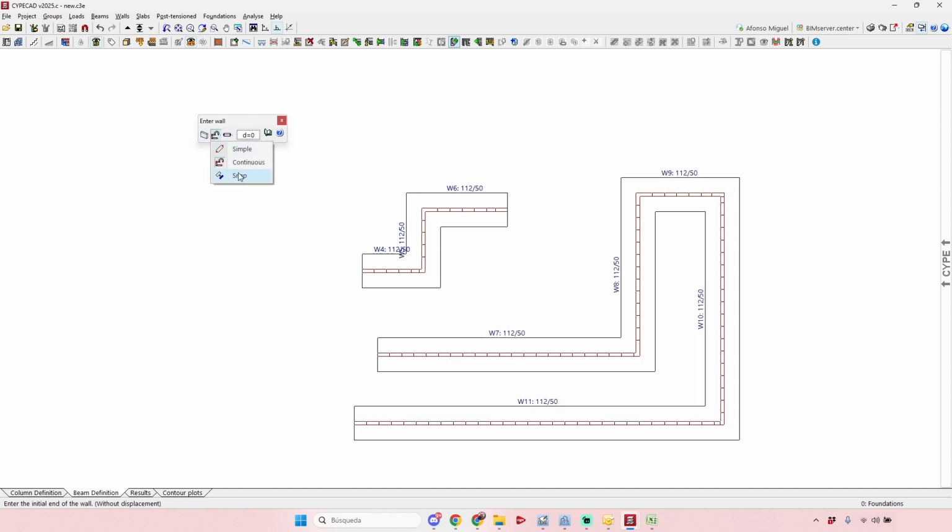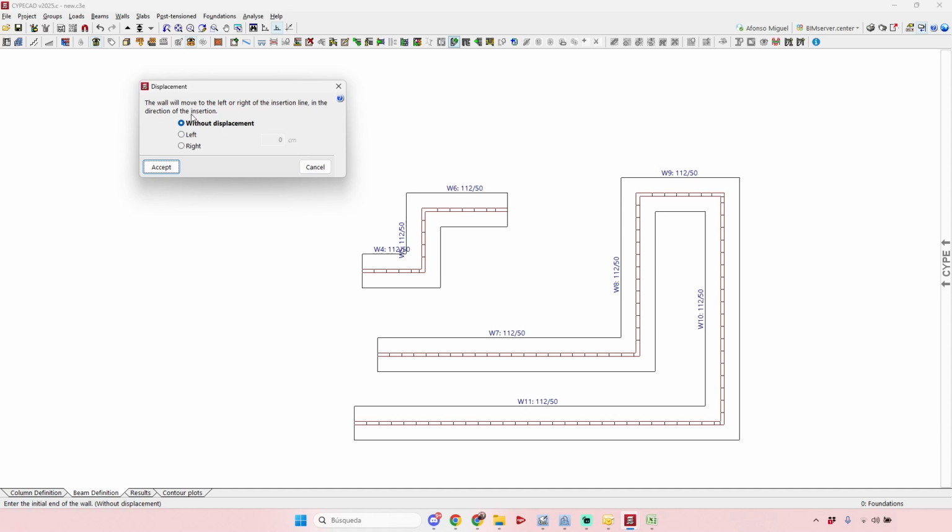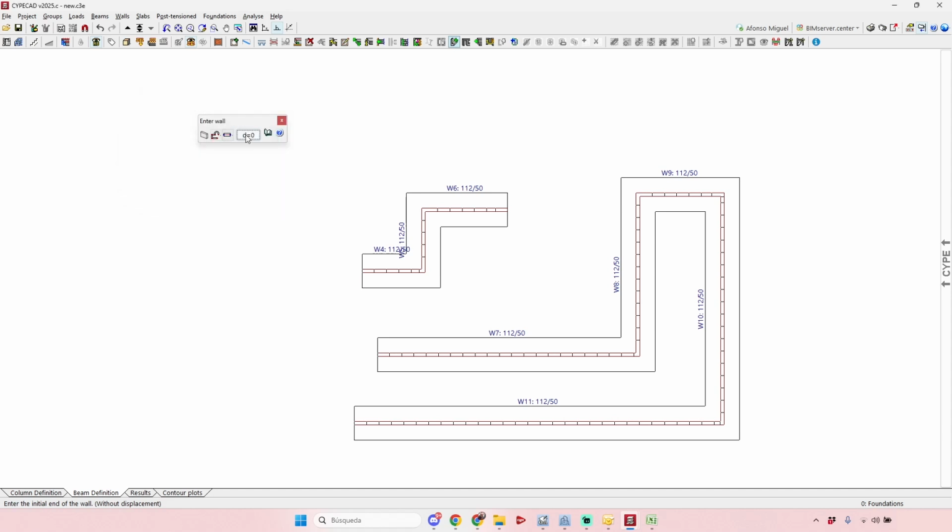And if we have a DWG file or a DXF file that was imported using the options that are here, we can snap these lines, these templates. So it's especially useful when you have, for example, curved lines or geometries that are a little bit different. You can also apply some adjusts on left, center, or right, and also considering a little displacement in these adjustments.